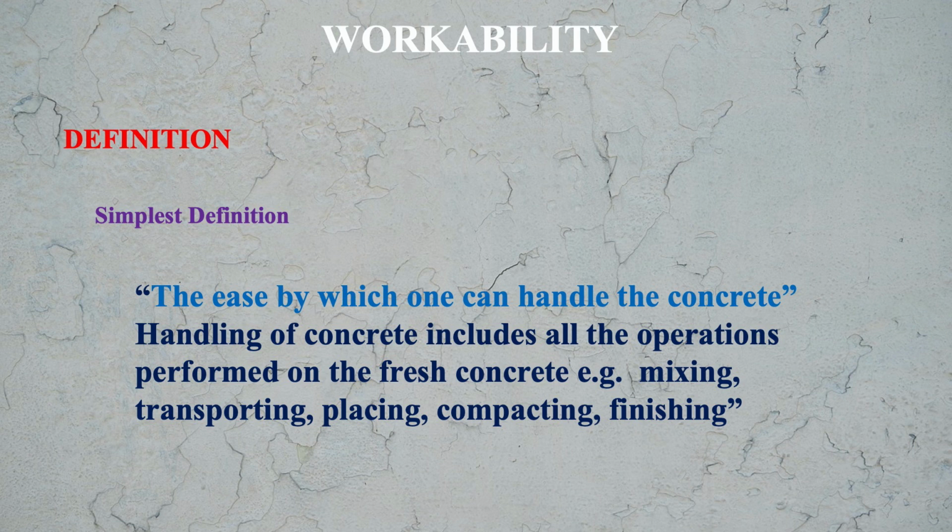The simplest definition I can begin with is that it is the ease with which one can handle the concrete. And as you know, handling of concrete includes all the operations performed on fresh concrete, that is mixing, transporting, placing, compacting and finishing. So you can say that it is the ease with which you can perform all the concreting operations.